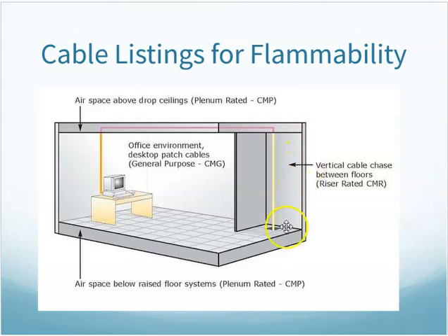If it is going to be installed between a closet on this floor and the data closet on the floor above it, if I'm going vertically between the closets, I need at least to be riser rated, CMR, riser rated, R for riser.